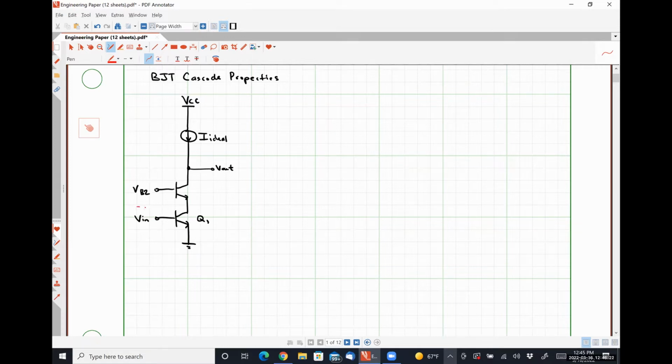If we put a box around this guy, where we are considering this node to be the output stage of transistor Q1 as an amplifier, if we ignore everything above the red box, what is this? Common emitter amplifier. Absolutely right. So we have a common emitter amplifier.